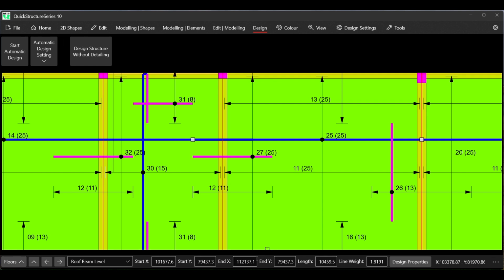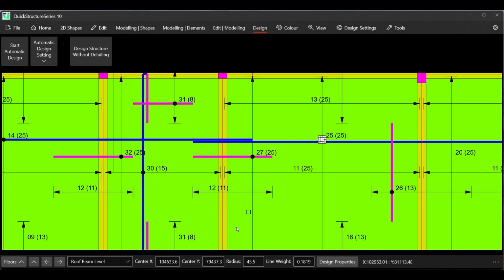We'll talk about that later. You can use the start point Y to do that. I can change the start point Y and move it down a little bit, say by 80. Then go back, change this to 80, and you can see the bar has stepped down. The same with this, I can change this to 80 also.